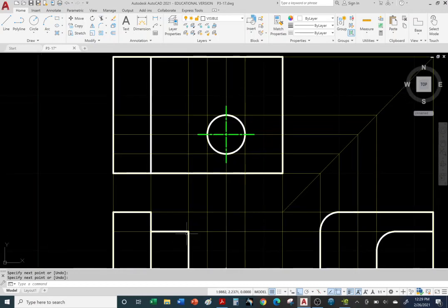Okay, so always when there's missing geometry, lines, curves, circles, always look at the other views and just project across. Okay, so I got this corner. Okay, let's go on to the next corner or vertex. Okay, I'm missing this one. Go straight up. And you're also going to go across. As you can see, it's already there for the right side view. Okay, so things are supposed to line up. Always go to the vertices and then project.